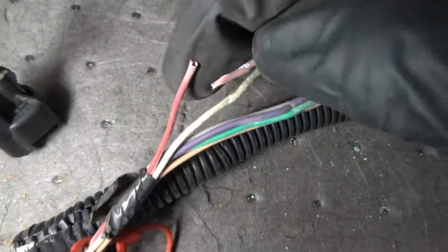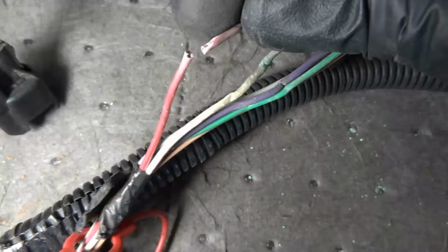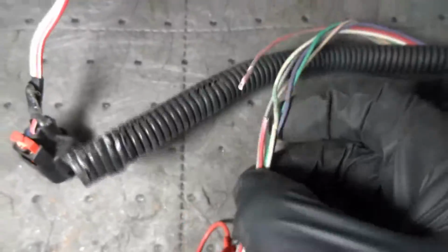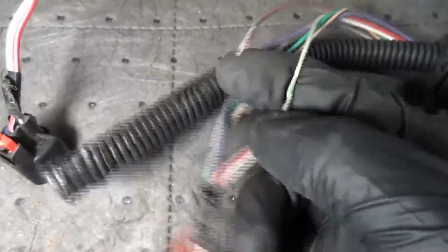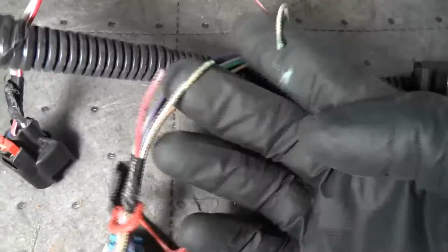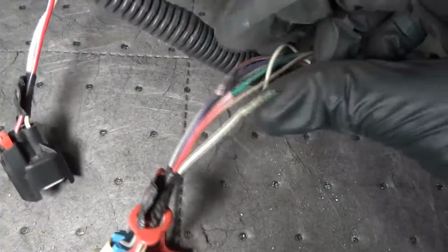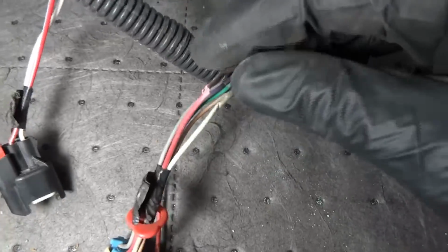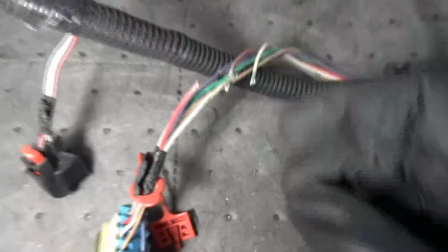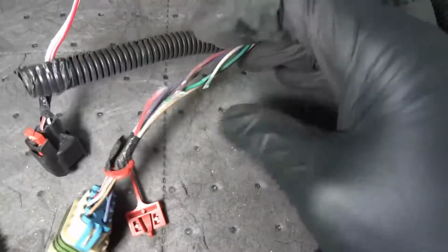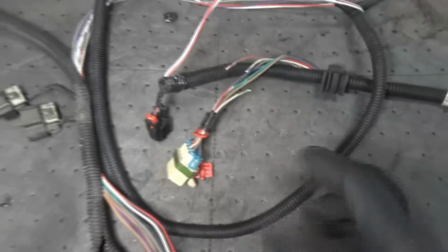You see that? So I just gave a little tug on this wire and it came out. So let me do the same thing on this one so you can see. Right there. You see this crusty green stuff? So this is what was causing the vent solenoid to not work. Okay? Look at all the green stuff coming out. So this is the problem, guys. So I'm going to fix these wires. I'm gonna fix them off camera. I'm gonna get all the wiring fixed.